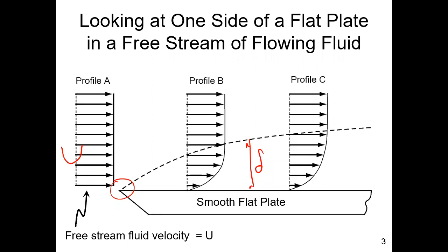And again, the boundary layer is a communication zone where through the fluid, there is a signal being communicated. What's that signal? Somewhere in the fluid, we have a different velocity than the free stream. It is a relative velocity issue, obviously. If this plate was moving at capital U in the same direction, you wouldn't have the boundary layer because there would be no difference in velocity. So that's all the background.